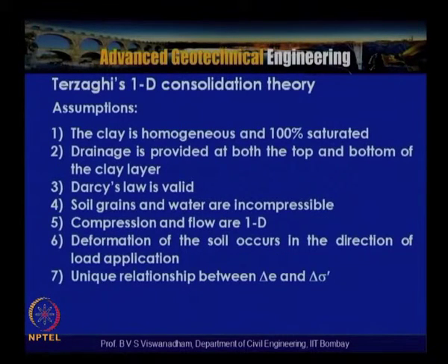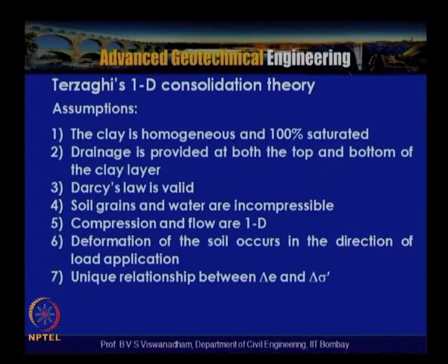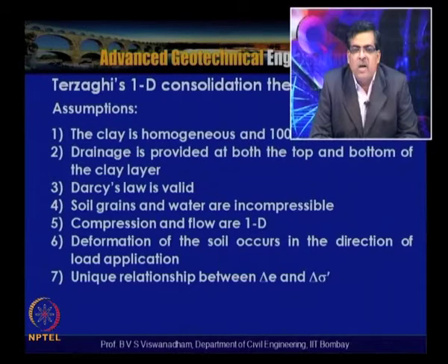So the Terzaghi's one-dimensional consolidation theory, basically the assumptions which are involved: the clay is homogeneous and 100% saturated, and the drainage is provided at both the top and bottom of the clay layer, and Darcy's law is valid. This is what has been assumed, but afterwards the theory can be derived for different boundary conditions. Darcy's law is assumed to be valid, and the soil grains and water are assumed to be incompressible, and compression and flow are one dimensional.